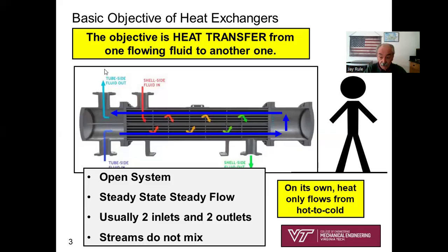So that's one fluid. The other fluid or substance is coming in hot, and it's coming into what we call the shell side. That's like the vessel part of the heat exchanger, and it's flowing up and down across these dividers, these dividing plates. So instead of just flowing in one direction, it goes up and down, like I'm showing with my cursor, so that it really mixes, it exchanges energy with the substance that's flowing through the inside of the tubes.